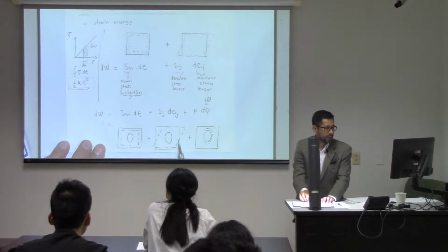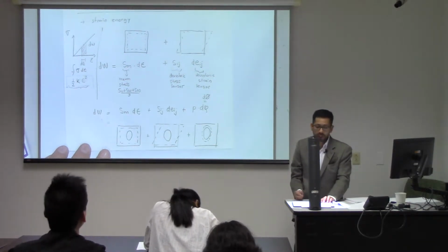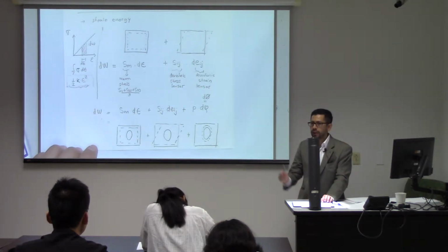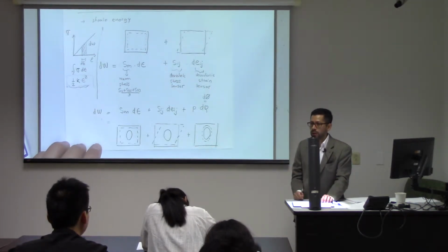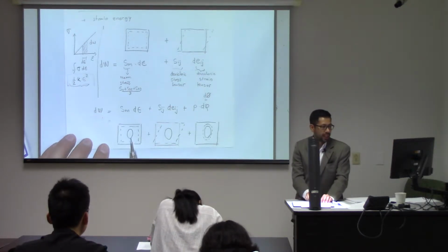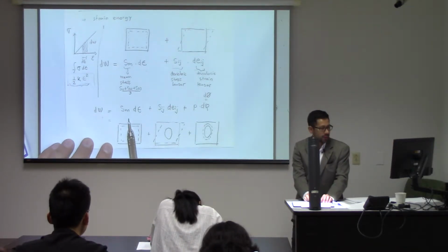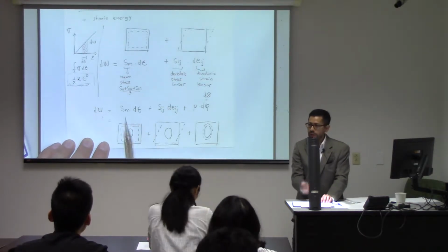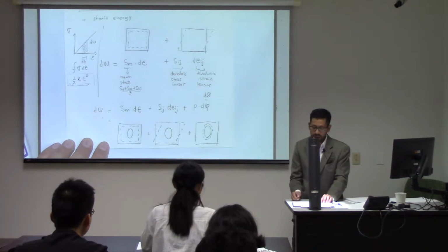we said that if we have a porous solid now, we have three ways of adding energy to the entire porous solid, counting the fluid inside as well. We can add a volumetric strain by means of the mean stress. Notice that shear stresses do not cause volumetric strains.